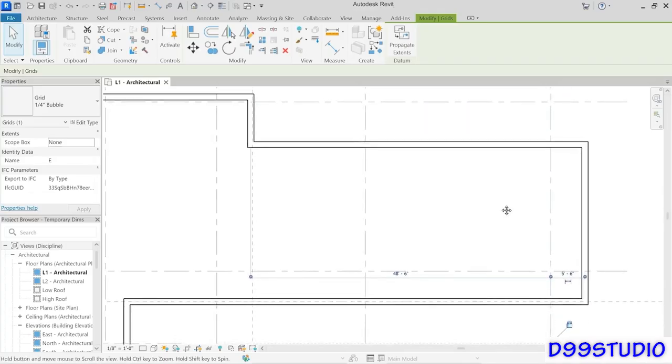Okay, now I'm going to select this one here. And the dimension appears across the bottom of my screen there. And it's very clear now, because I'm zoomed in a little closer, that the witness line is in the center of the wall. Okay, but it turns out we can actually relocate that. So notice these little dots that appear on the witness lines. And if I put my mouse there, there's actually a tooltip that says move witness line. If you simply click the dot, that witness line will jump to a new location. It went to the inside face in this case.